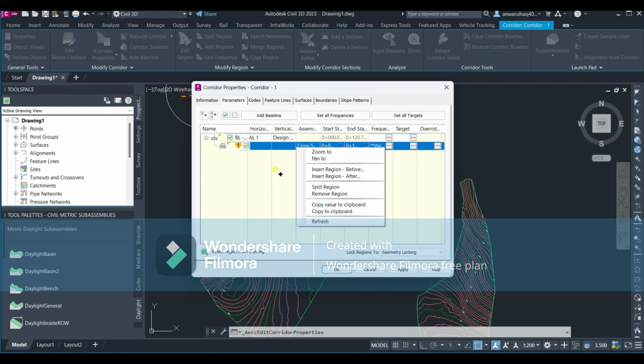If you have tunnels or bridges, you get many cross sections, so you can insert a region for them at limited RDs, because the alignment runs from 0 to the total length of the alignment. There are sections, or you have provided the labels with the RDs, so you can insert your road, your bridge, your underpass, your tunnel with that RD.